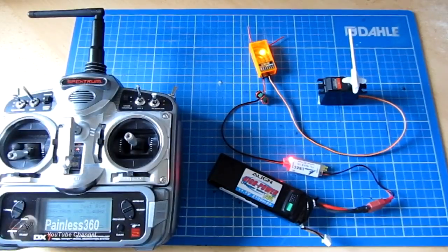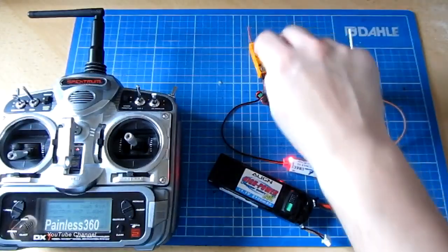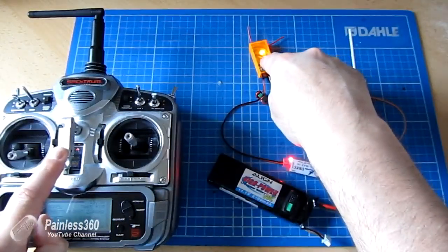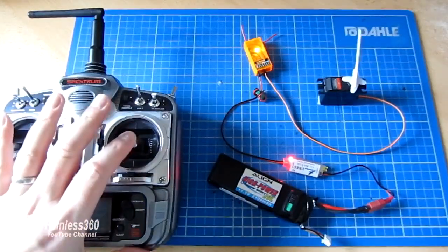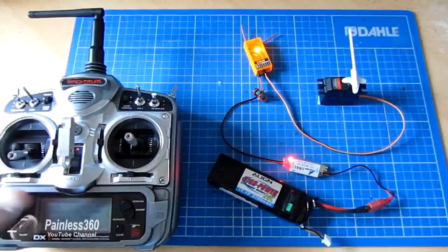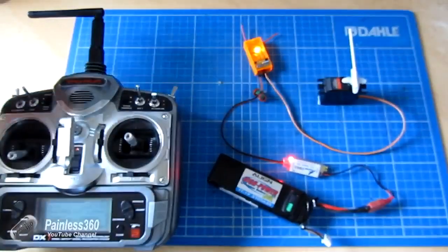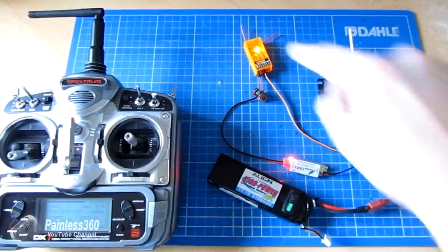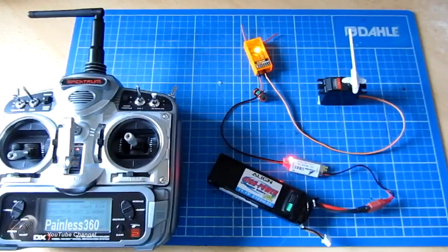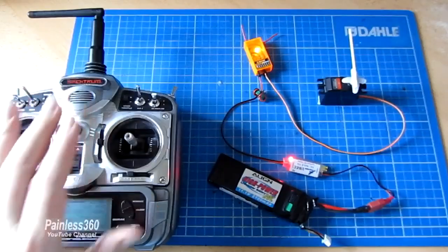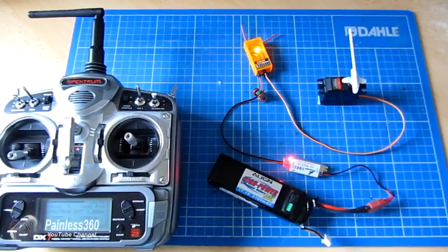Now I'm not going to go into too much detail about how all that works. If you're really interested, you can look at the wikis and Google it and find out about it. But suffice it to say that with the radio and the receiver, I'm not just sending one continuous stream of positions, I'm actually encoding the information digitally, surrounding it with error checking code, and then it's going out to the receiver. And if the receiver and the radio, when they power up, have a noisy environment, they'll hunt around on the 2.4 gigahertz frequencies they can use until they find one that works.